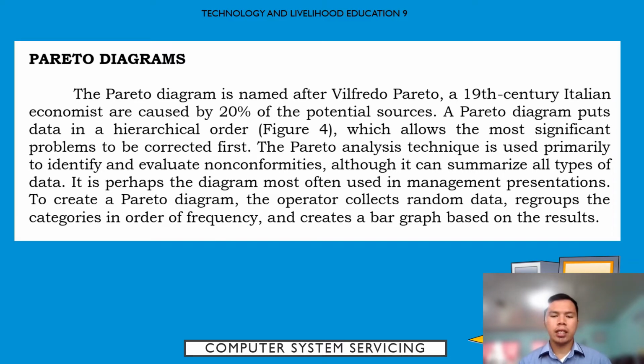The Pareto analysis technique is used primarily to identify and evaluate non-conformities. Although it can summarize all types of data, it is perhaps the diagram most often used in management presentations. To create a Pareto diagram, the operator collects random data, regroups the categories in order of frequency, and creates a bar graph based on the result. So the result of check sheets can also be turned into a Pareto diagram.